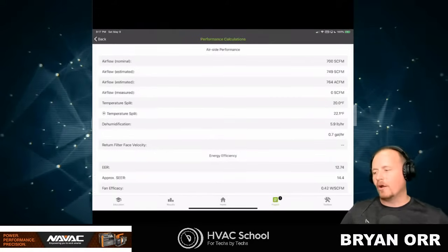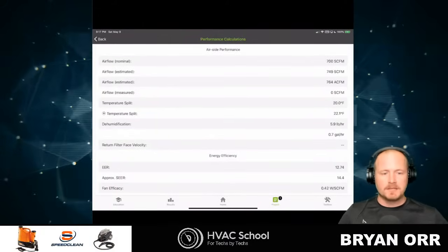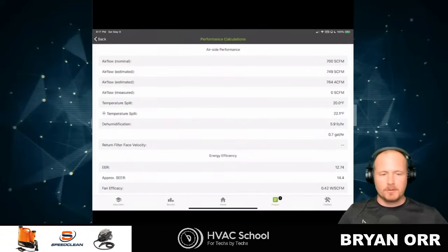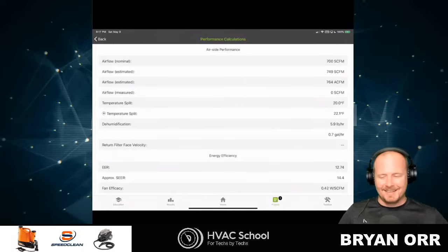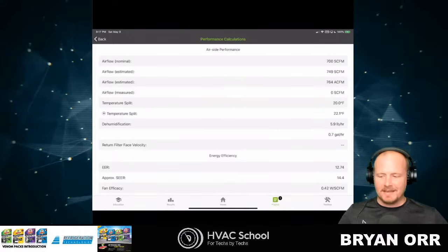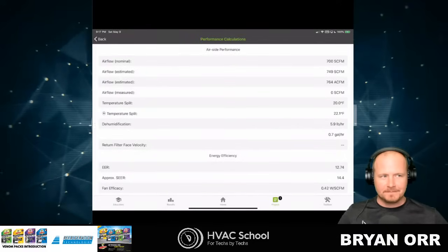Yeah, one question I get all the time, which I never really have a great answer to, is what's the difference between liquid line pressure and discharge line pressure? And I just say 11 pounds. Is that a real answer, or you're just making that up? About 10 to 11 pounds.